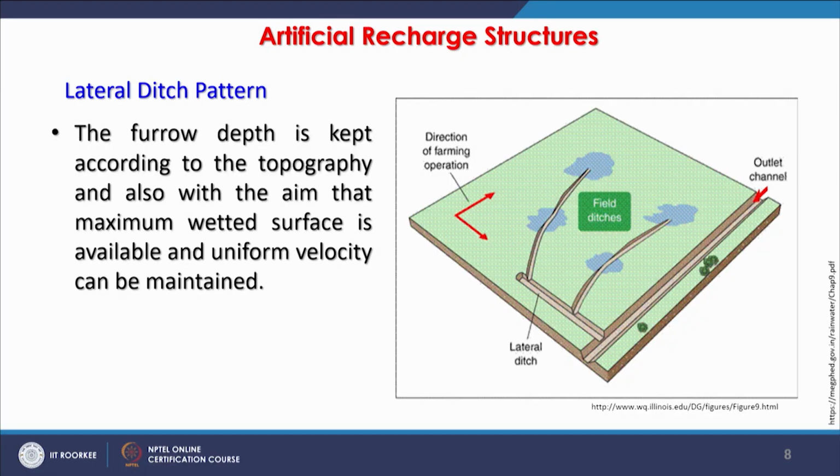Another type of approach for ditches is lateral. So, in lateral ditches the furrow depth is kept according to the topography and also with the aim that maximum wetted surface is available, because with more wetted surface, there is a possibility of more infiltration and then percolation.